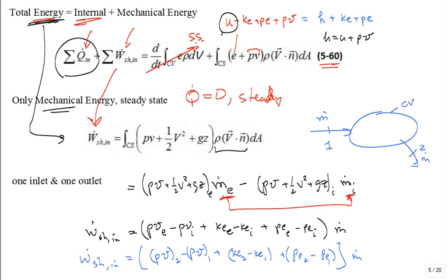You can think about this representing a pump. And a pump, yeah, you have to supply shaft work into the pump. What's the purpose of the pump? The purpose of the pump typically is not to change the kinetic energy of the fluid or to change the potential energy of the fluid, and not even to change the specific volume of a liquid. Usually pumps apply to liquids, but it's to change the pressure. And so you can go back and revisit problems that you've solved in thermo.